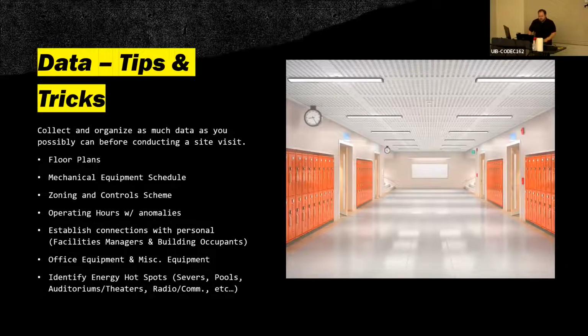So a lot of that, we're going to shift gears now into actually going and conducting the benchmark. So data, we're going to go over some tips and tricks. You want to collect as much data as you can before you go to the site. So before you go to the site, try to secure floor plans, mechanical plans, zoning and control schemes, and operating hours with anomalies. Are they holding a drill once a month on a Saturday? Is there an employee training session that happens every other quarter, or things like that?